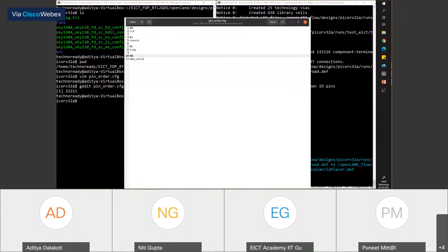So it's all about how you floor plan the internal design, or how the tool will floor plan the internal design. And that's why I said this whole thing is an iterative process. You might run the design once and then go again, change some of these pin locations, and rerun the design to do this better next time.